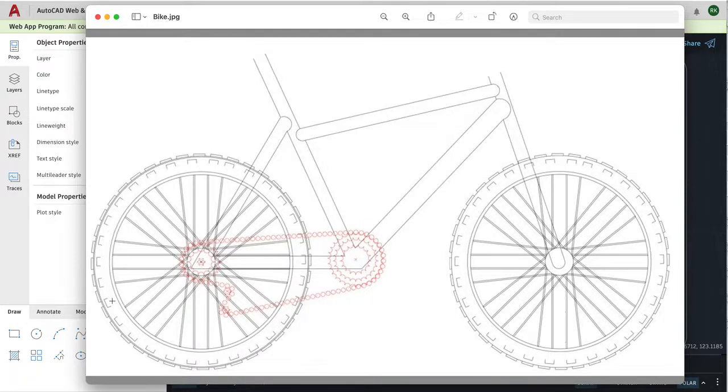And in doing this, we're going to learn how to use the array tool, the polar array tool, the mirror tool, and we'll use other tools we're already familiar with, such as drawing our lines, drawing our shapes, using trimming, using offsetting. So we're going to start with drawing one of these wheels. Our goal eventually is to get to the point where we have a bicycle frame with two wheels, and we have our back cogs and our front cogs, and we also have a chain.